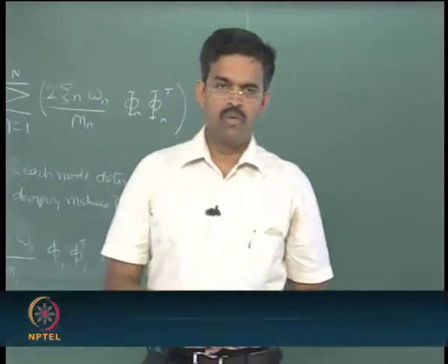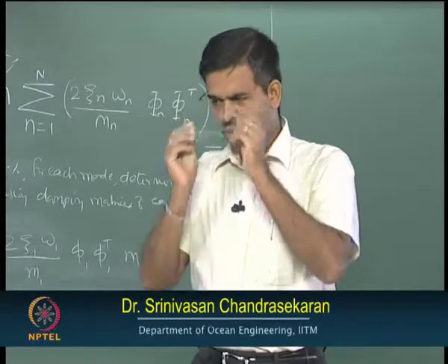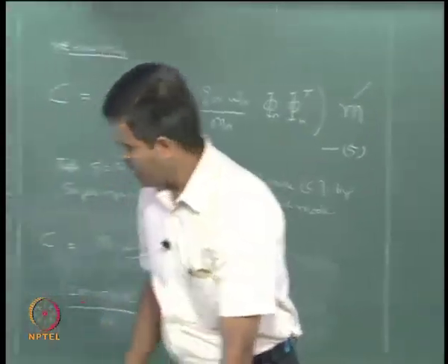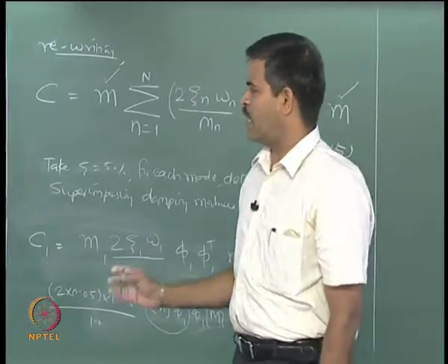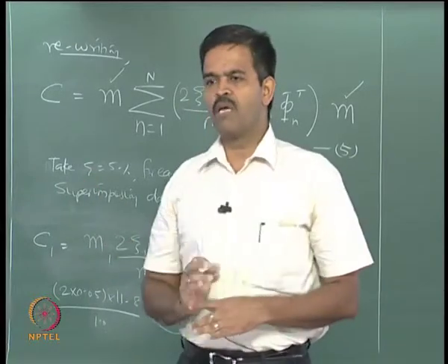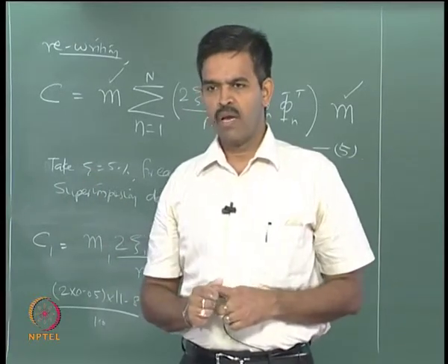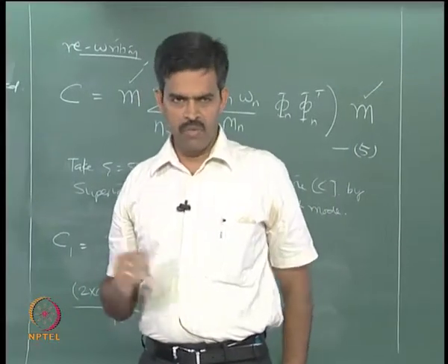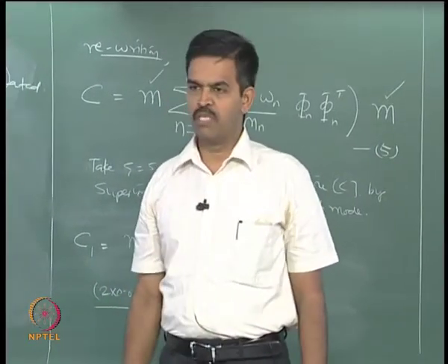So, try to look at the literature and try to understand it, because what we have seen in this lecture, or in the couple of lectures, is how to estimate the damping, K and M from first principles, how a new geometric form can be attempted for a dynamic analysis, and how the equation of motion can be solved using a time stepping procedure, which we will discuss in the next lecture tomorrow using Newmark's beta method.